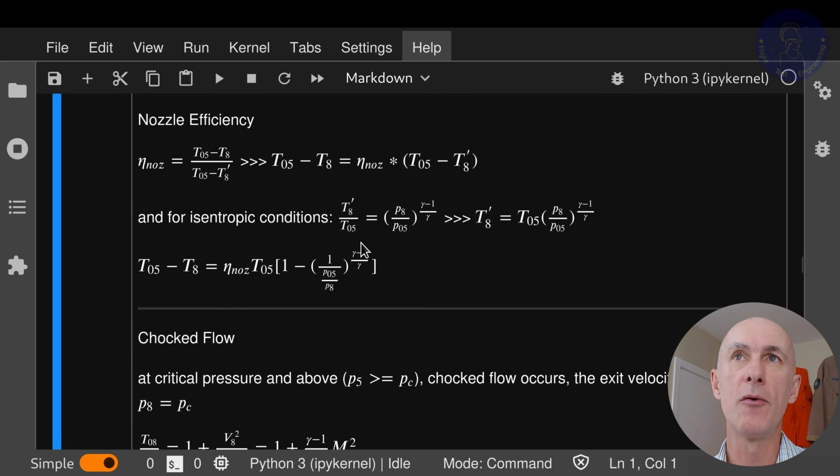If we recall the isentropic pressure-temperature change relationship, we can include the pressure ratio in our equation. And why is this important? Well, because that is easy to get from our nozzle conditions. At the end of the day, the exhaust gas going through the turbine will result in a pressure drop, and since the next step is to expand to ambient pressure, we have the pressure ratio defined. With this, we will be able to calculate the exit temperature given the pressure ratio.